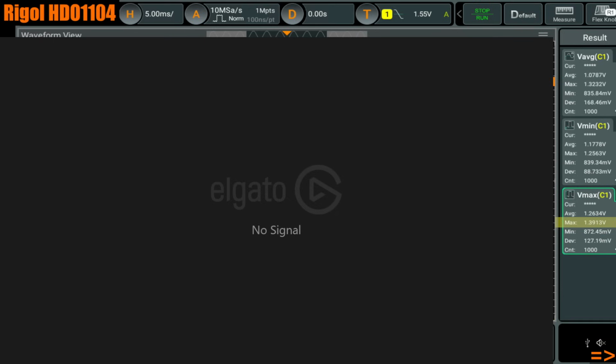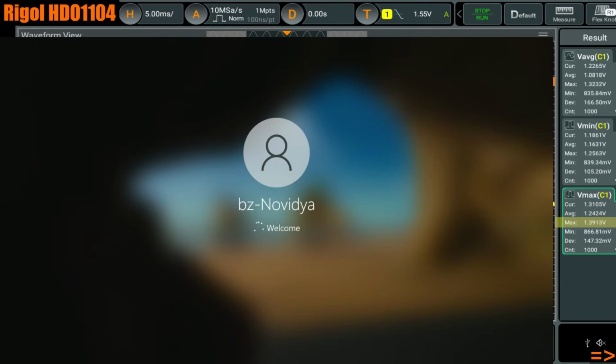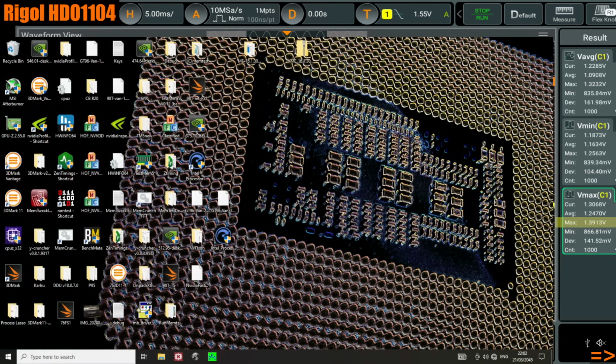And that's the thing with undervolts: the more you push this down, the more likely your system is to not work correctly. You're going to be back to where we were with the undervolted out-of-the-box motherboard BIOSes, where you could buy a brand new CPU and it wouldn't be able to run Cinebench because your motherboard was applying like 160 millivolts of negative offset at high currents.